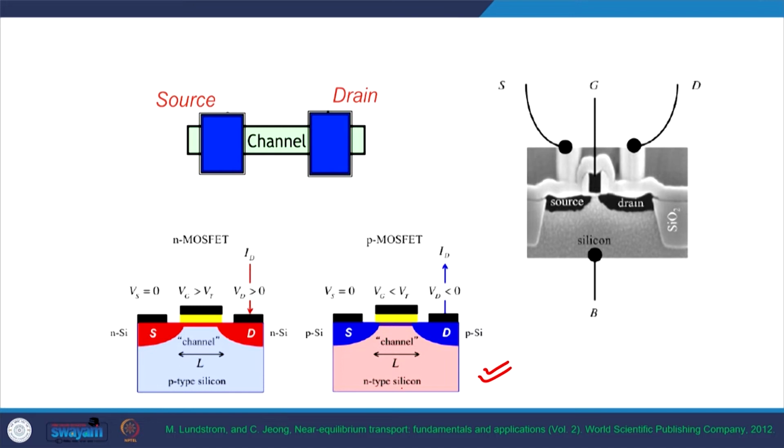So this is how it is drawn when we try to understand the MOSFET, and there can be two types of MOSFETs. One is the NMOS and second is PMOS. In NMOS the channel is an N-type channel made out of electrons, and the substrate or the body is P-type silicon, on which by applying a voltage on the gate terminal, or by applying an electric field on the gate terminal, we can make an inversion layer inside the material.